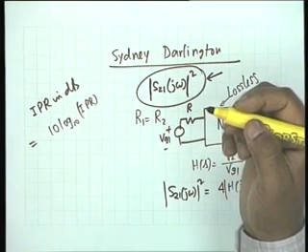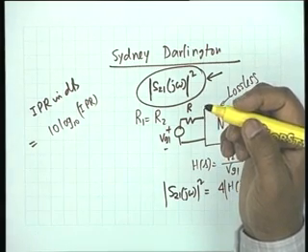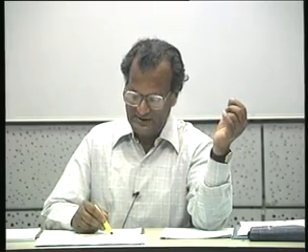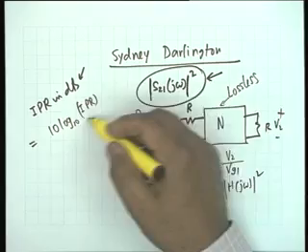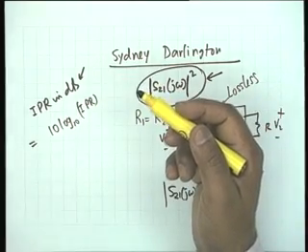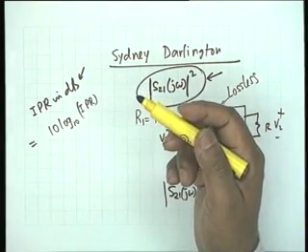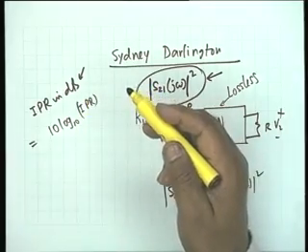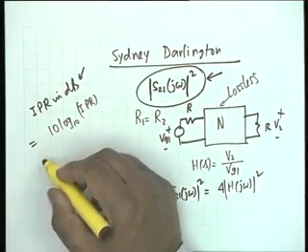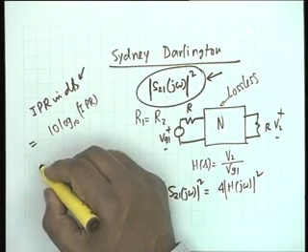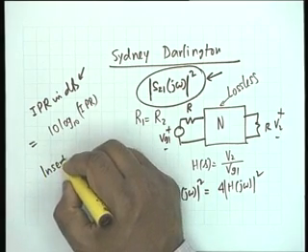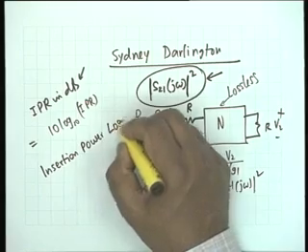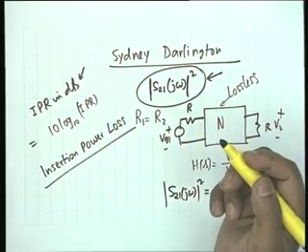Okay, insertion power ratio is P20, that is the power without the network, divided by the power with the network. So, if this is given in decibels, then you have to find out the IPR by taking the ordinary ratio, that is decibel divided by 10 and then 10 to the power that. Okay, and this is sometimes in the literature called the insertion power loss.